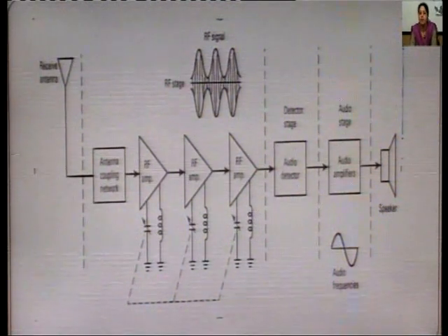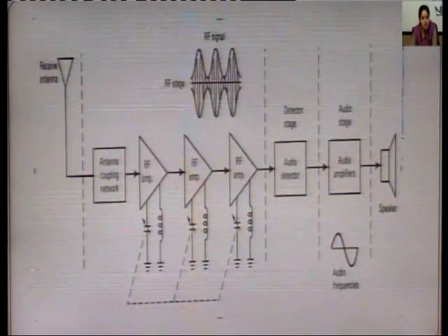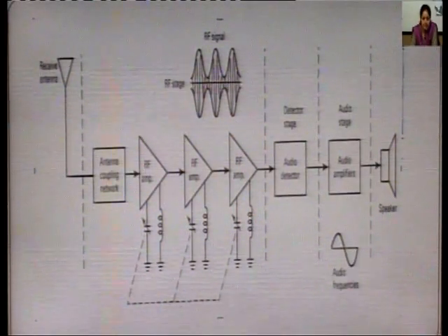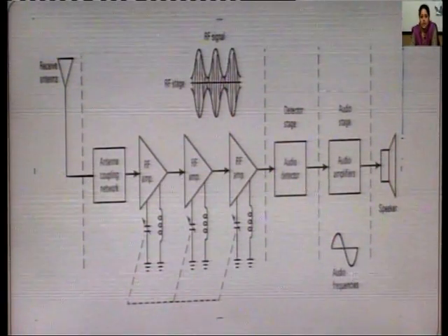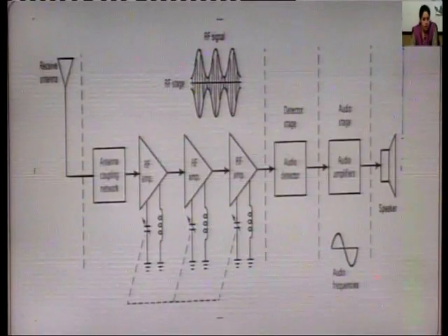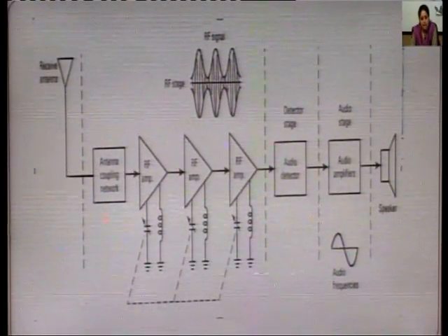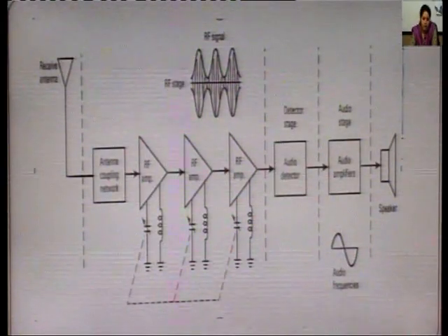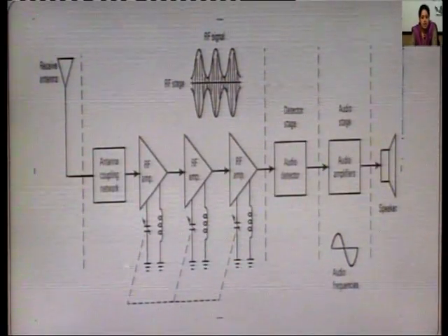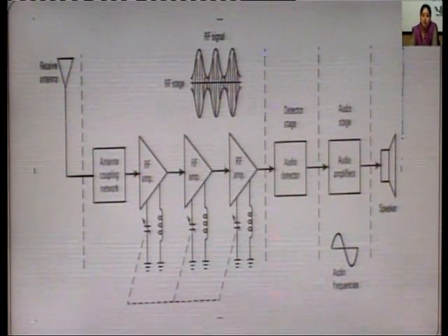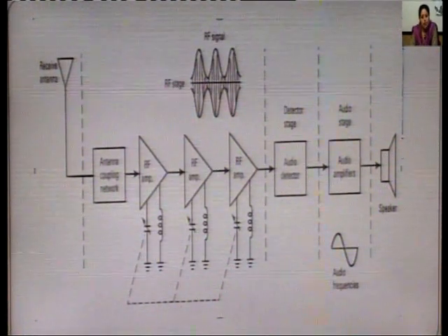After the RF amplifier, you have selected the particular frequency and amplified it, and it is given to the audio detector. This is the detector stage. As we have discussed, this detector stage demodulates your signal. According to your application, it can be any detector, as you are dealing with AM or FM or other particular receivers. For AM and FM you have various detectors, such as the balanced modulator and the slope detector. There are various detectors. At last, it is given to the audio amplifier stage.